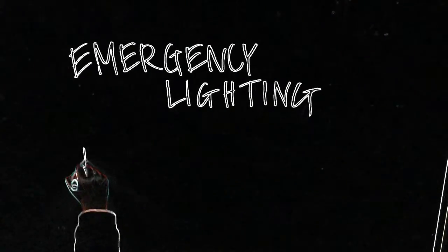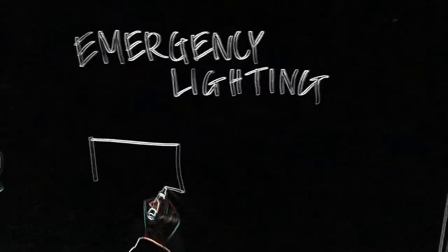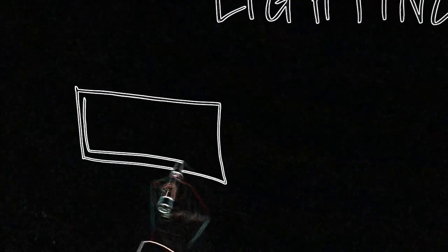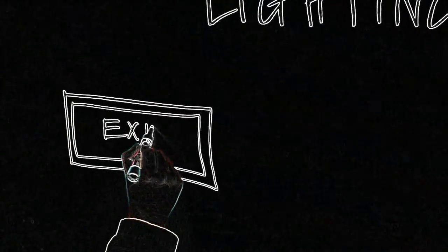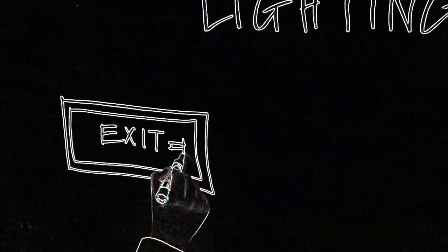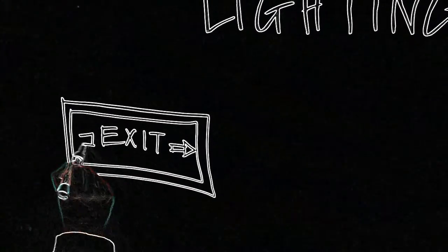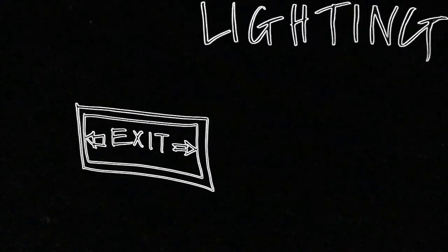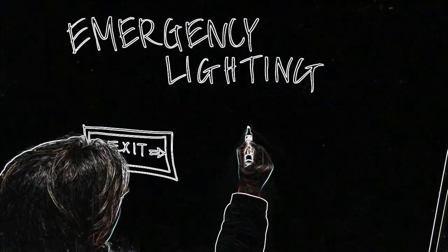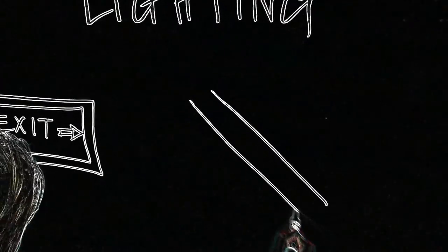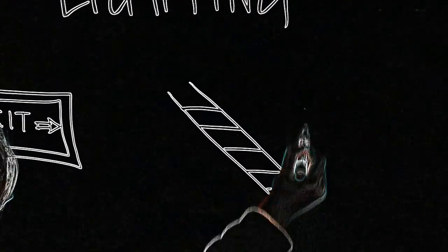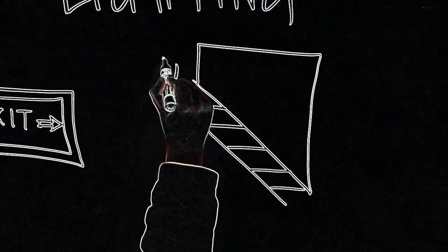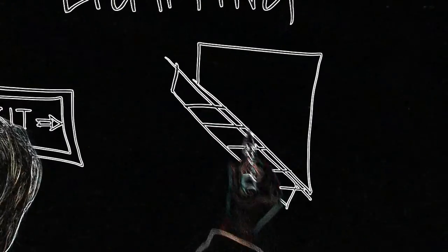Emergency lighting. Like exit signage, emergency lighting is typically required whenever two or more exits are present. Sometimes referred to as exit lighting, emergency lighting must be connected to a backup system in case of power failure during an emergency. This could mean connection to a backup generator in the building or battery packs located within the light fixture. Generally, the codes require emergency lighting to be provided at all exits and any aisles, corridors, passageways, ramps, and lobbies leading to an exit.